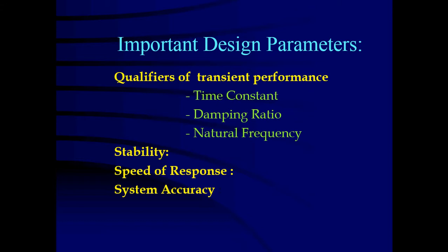When we are in Simulink, this is where we say, oh, the time constant is too small or too big, or the damping ratio is this or that. Perhaps one thing about the natural frequency, we briefly mentioned that, remember the characteristic equation is the denominator of the transfer function, right? The roots of that equation are the natural frequencies of your system.